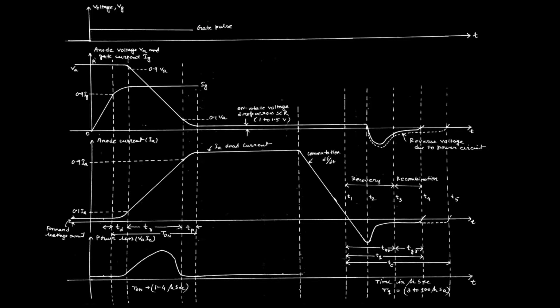One thing to keep in mind: once the thyristor starts conducting, once the anode current starts flowing through the junctions and reaches the latching current IL, then we can remove the gate from the terminal. Still, the device will remain under conduction, or the device stays in the on state. Then the gate will not influence the conduction process. That means the gate is required only during initialization of the turn on process. Once the thyristor starts conducting, we can remove the gate from the thyristor.